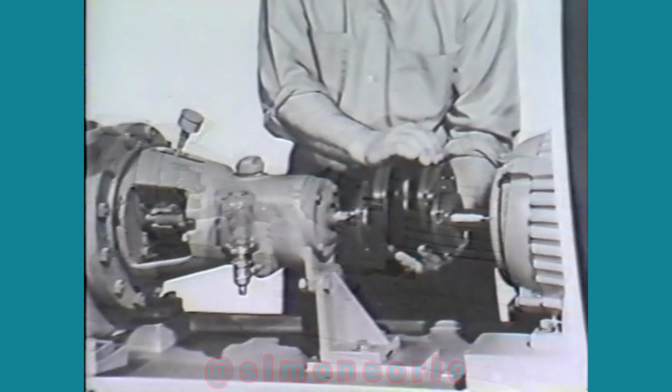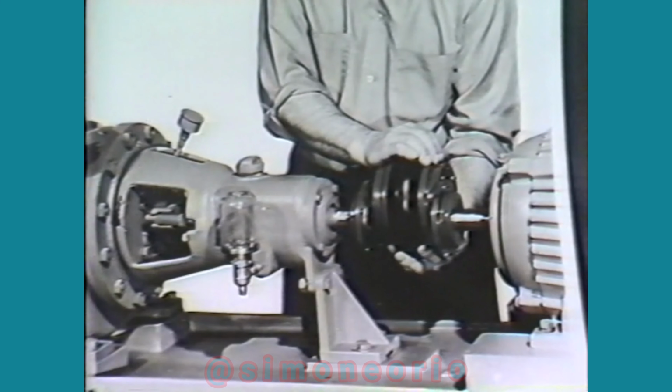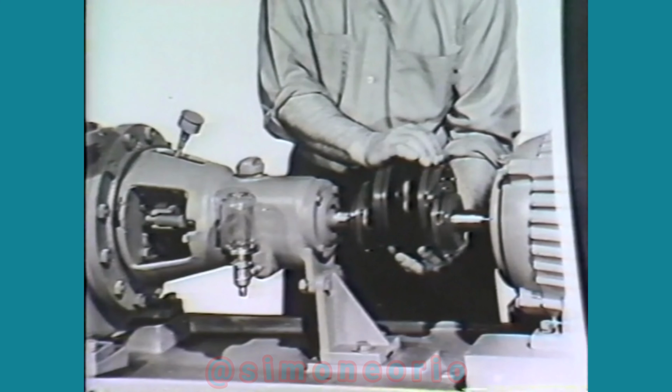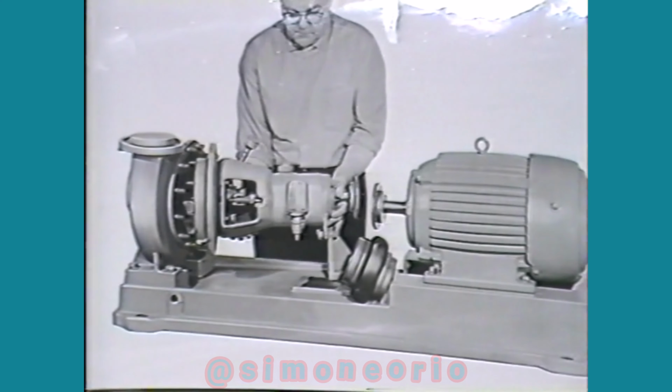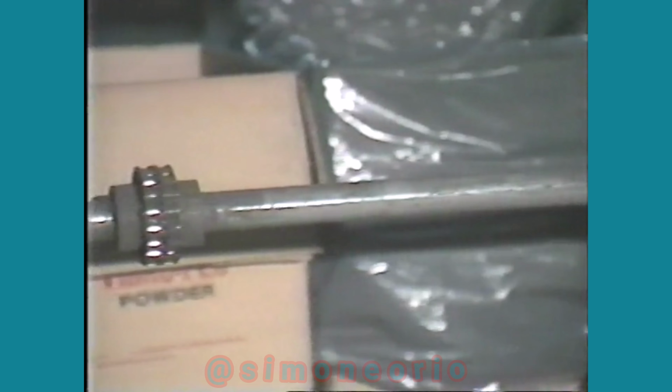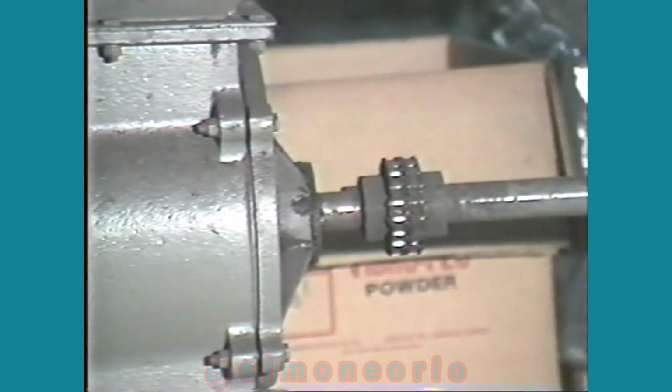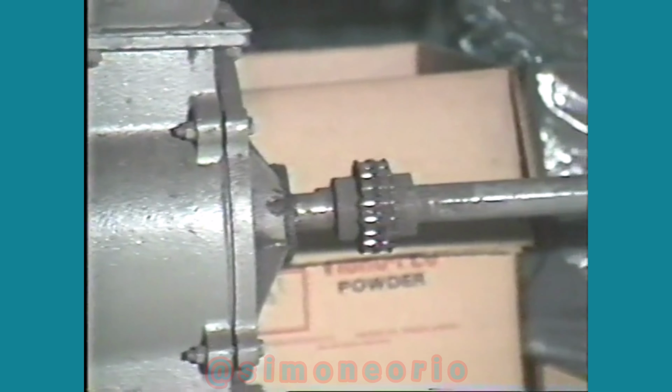By dropping out the spacer part of the coupling, there is now room to remove the pump face. Inspection and repair may now be done. The hubs of the spacer coupling were left in place. No realignment or moving of the equipment is required for servicing because of the spacer coupling design. Where even more room is desired or necessary between shafts, this arrangement is convenient.